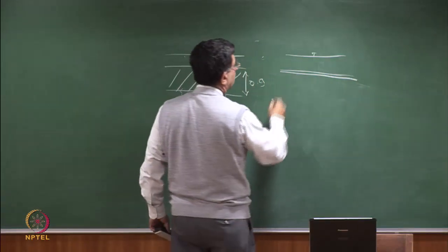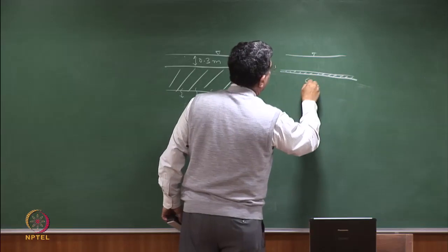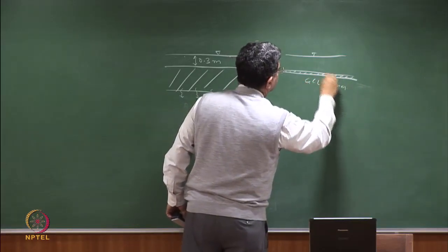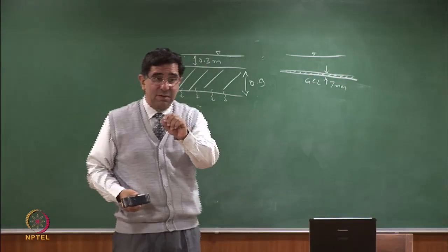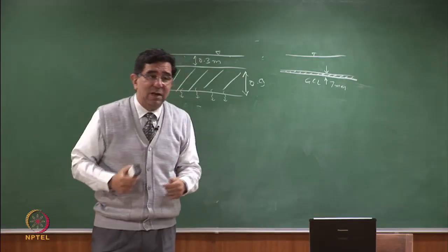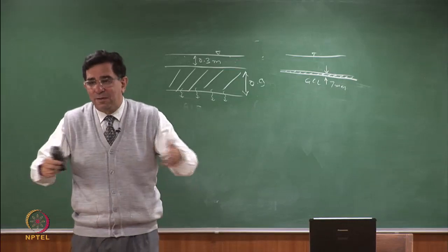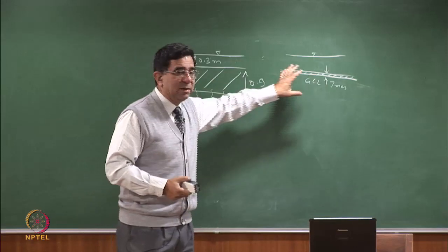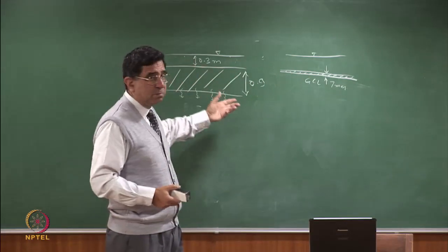that is your seven millimeters. It's thicker than a geomembrane, which is 1.5 mm. But the GCL is supposed to be self-healing. So if you have a puncture, the bentonite will expand and heal itself. So we are going to now compare the Q through both of them, right? But this problem is presented.